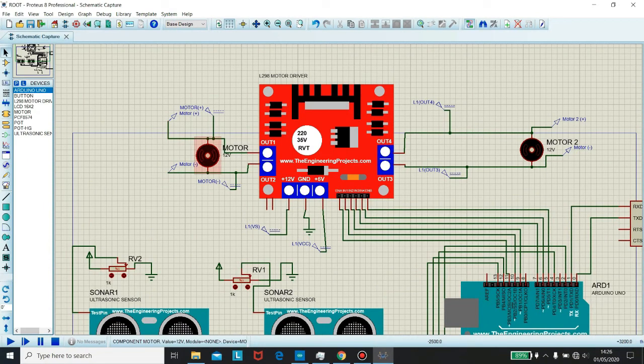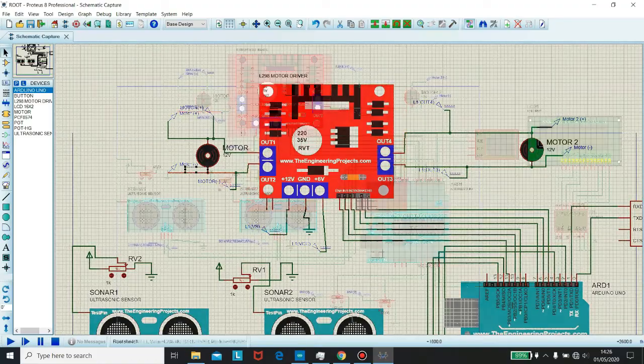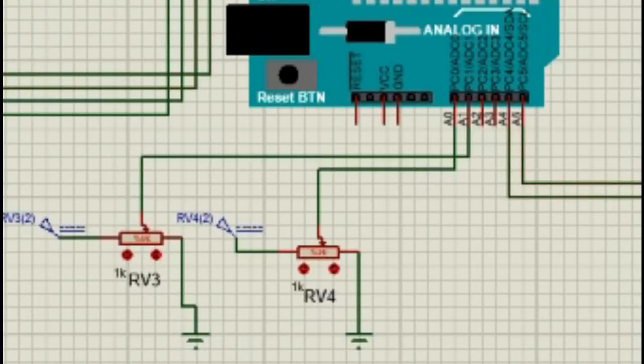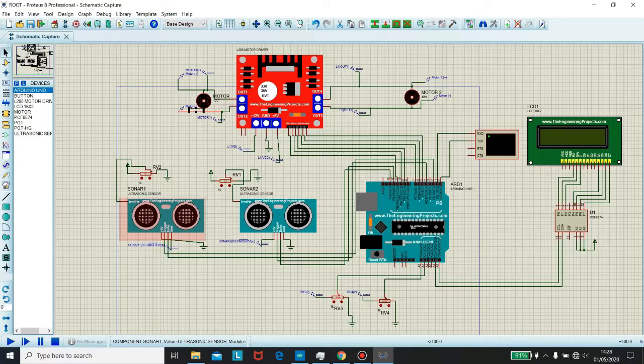Two DC motors connected to a set of gears act as components to drive the door. For that, we configure the control with the motor driver for easy control of the speed and direction of rotation. Then one potentiometer functions to regulate the speed of the motor connected to the analog pin on the Arduino, while the other potentiometer functions as a PID set point tuning, which is a conventional control method to get a better system response. To make it easier to understand this, let's try to observe the real simulation.